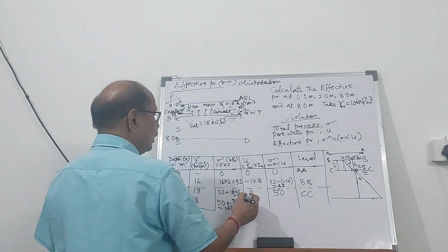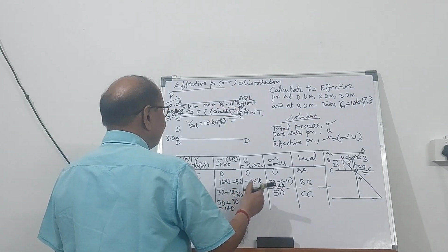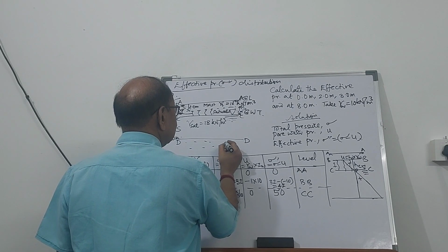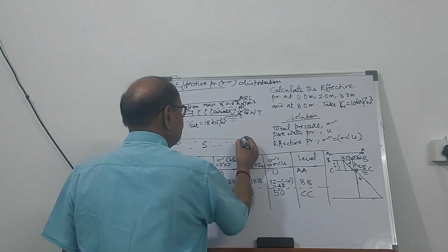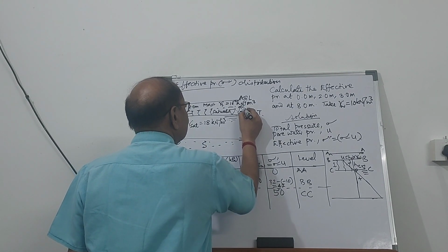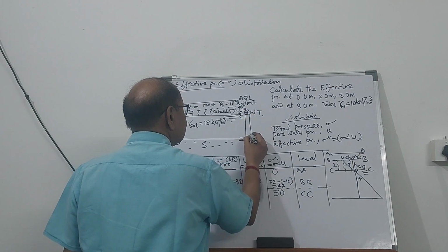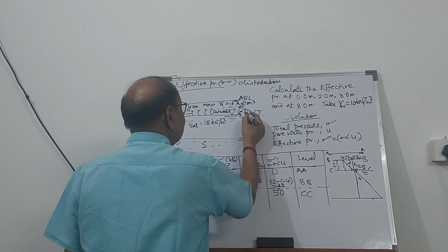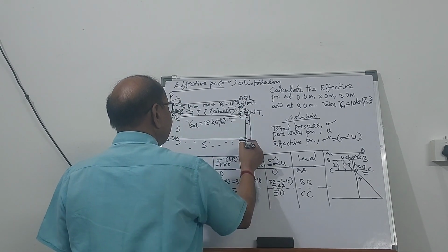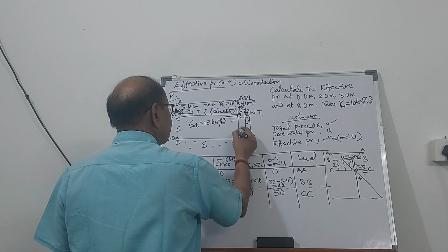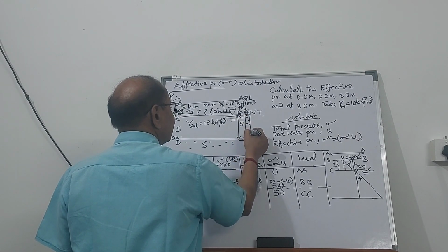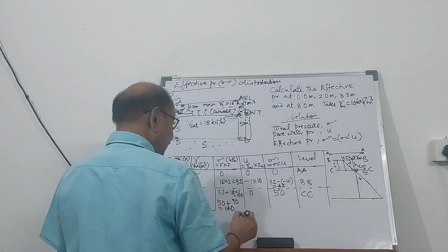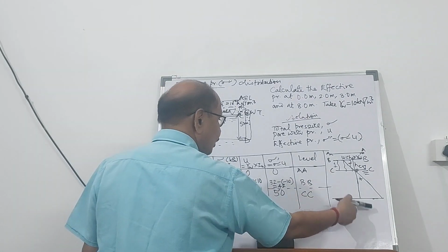Right? And what is the pore water pressure? When you put a piezometric tube here at this level, the water will rise in the piezometric tube, in the piezometer, up to this level. So there is 5 meter. So water in the standpipe or in the piezometer goes up by 5 meter, and this is going to be positive.